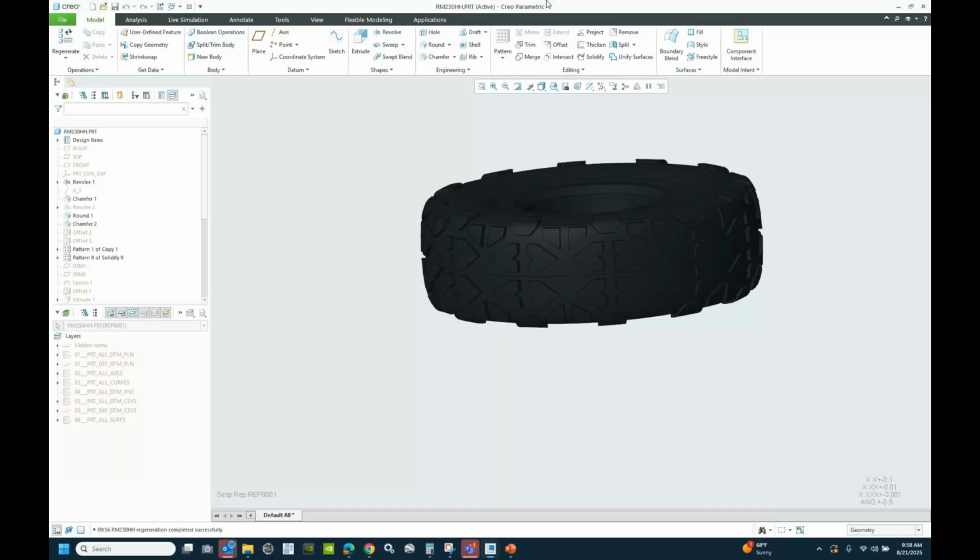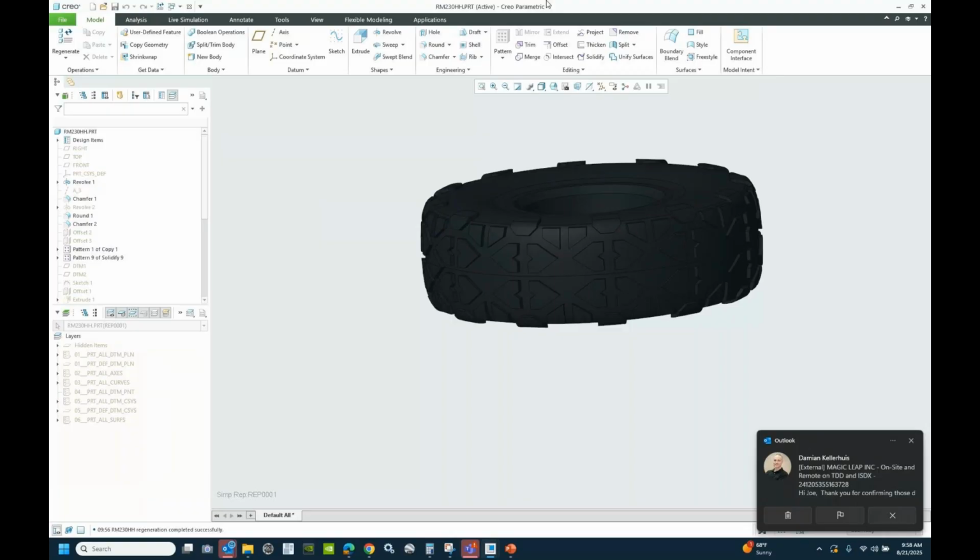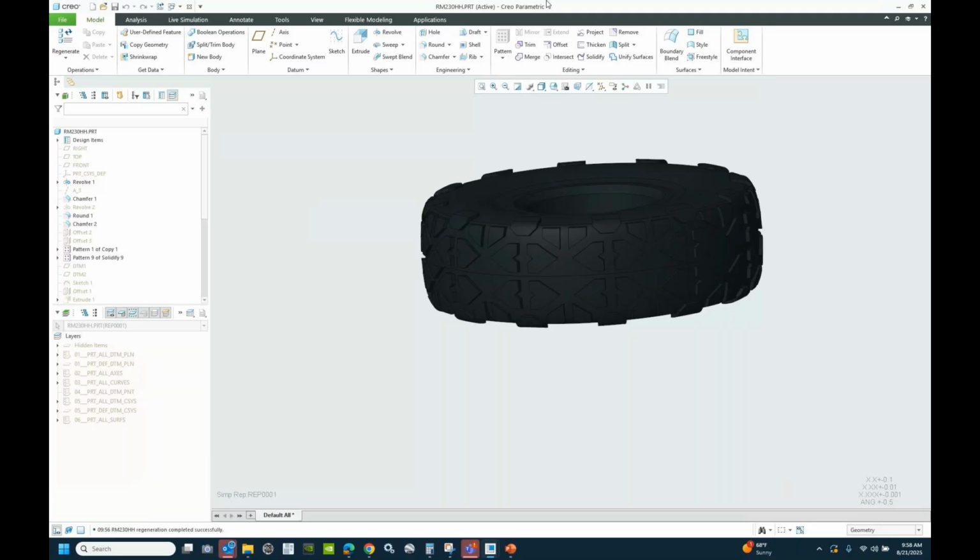Anthony asked, can we make reps in the assemblies? But when we get to the assembly drawing with different sheets and different reps, this seems to fall down. So in the drawing, and this is typical of a sheet metal part, the sheet metal tools in the newer versions of Creo actually allow you to create a simplified rep for the flat pattern, right? Because in a sheet metal drawing, we typically want to show the bent up state as well as the flat pattern, and so we can set the rep for an individual view.